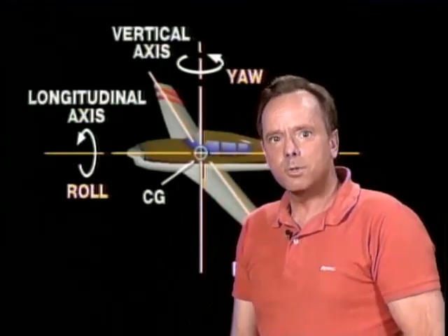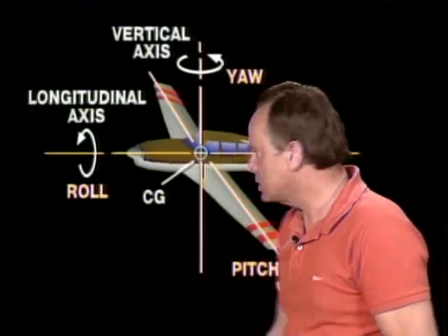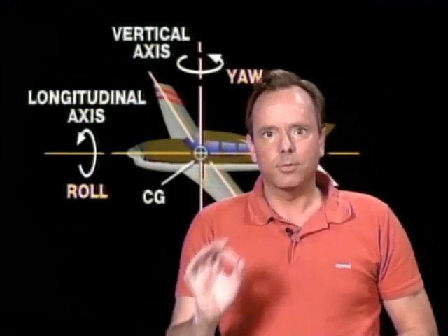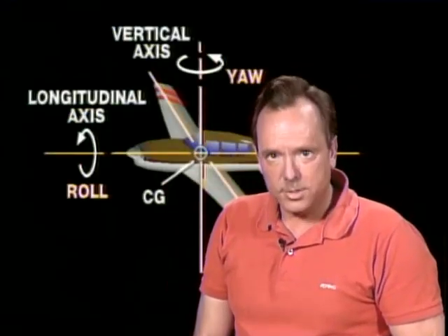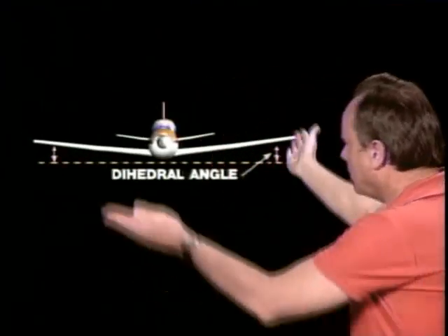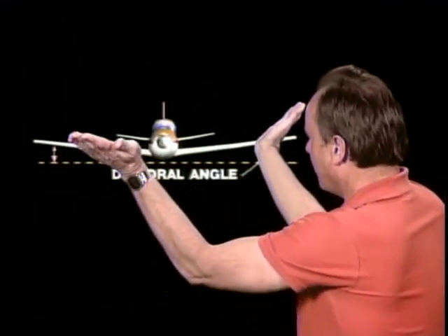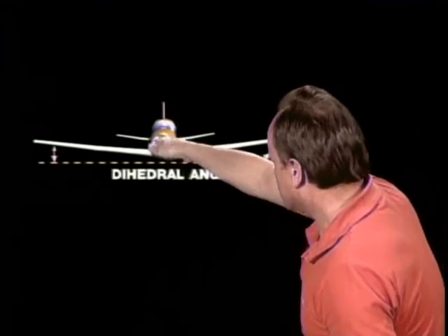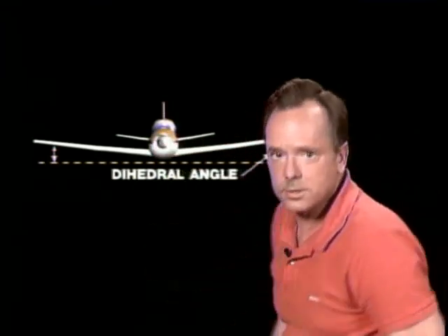So lateral stability is stability about the axis which runs parallel to the line of flight, and it's referred to as lateral stability. Now, let's take a look at lateral dihedral. Dihedral contributes most of the stability of an airplane about its longitudinal axis. Now here's dihedral, and it's the bending up of the wings, and it has to do with stability about the longitudinal axis of the aircraft. That's that same axis we talked about earlier.